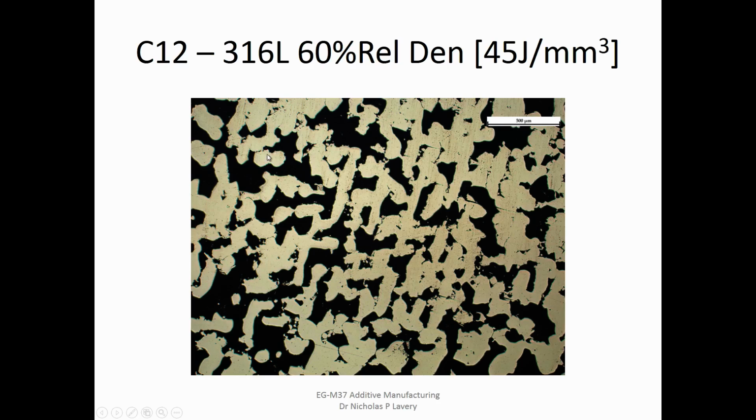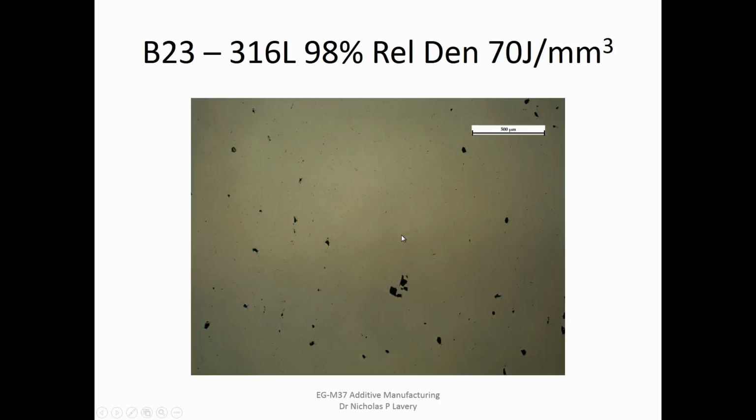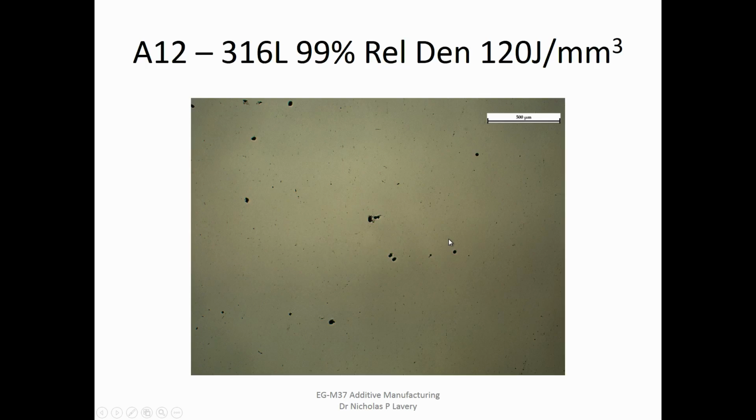Let's just show you some of the porosity, and you can see unmelted powder particles in there. You can see the individual directions in which the laser has moved on this, and the sort of interstitial non-coverage of the laser, which leads to these. These are quite large pores, quite angular and jagged as well, which are going to give you stress concentrations when you go on to do your tensile tests. As you get up to your more optimal settings, here you are, one of the better ones, your porosity sizes go right down.